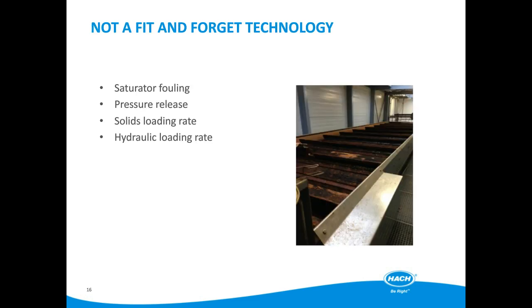DAF tanks do need maintenance. Because packed saturator tanks use effluent from the DAF tank, this recycled water can contain nutrients, which encourages the biomass to grow on the surface of the packed material. As there is a plentiful supply of oxygen and a warm environment, over time this build-up of biomass will cover the surface of the inert material, reducing the surface area of water in contact with the compressed air, and hence reduce the absorption of gas into the recycled water, and therefore the saturation efficiency.